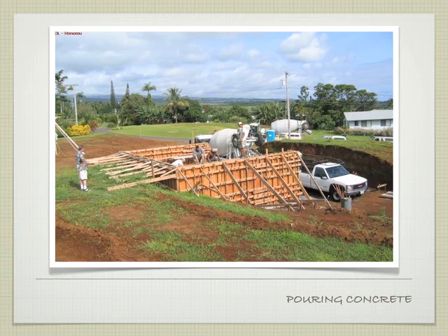They try very, very hard to reuse as much of the wood as possible. Even if you're doing smaller foundations, chances are you will try to reuse it, especially if your engineer will allow it. Let's say you're building foundations for your house. You did 2x12 formwork on the outside. You'll reuse those as some of your floor joists on your ground floor or something like that. So you try to reuse as much of it as possible and not throw it away, right?